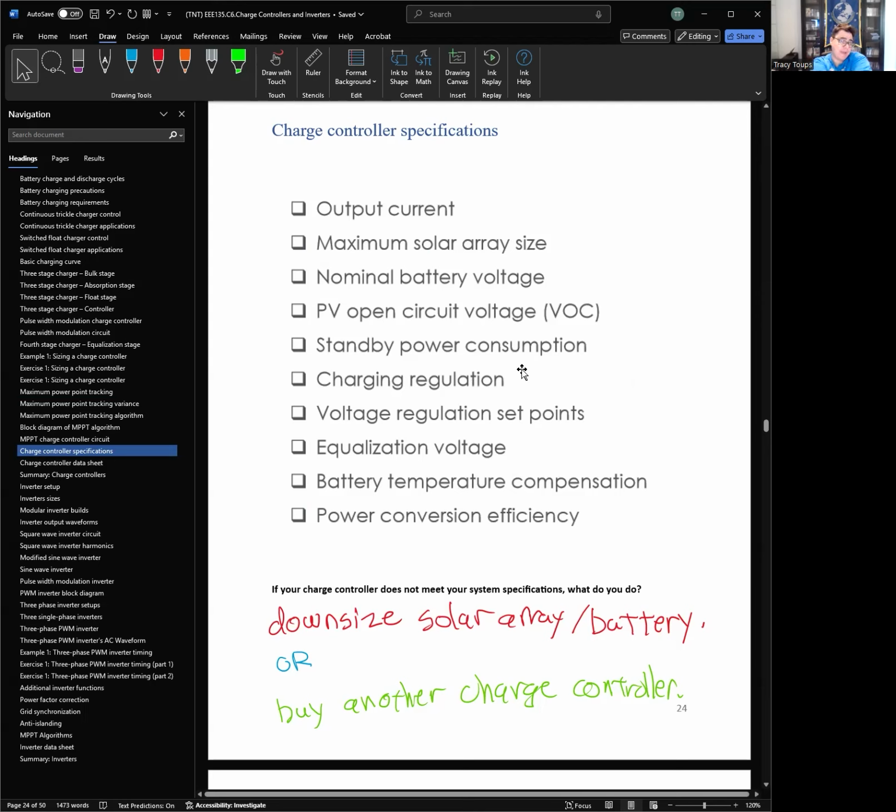So let's say nothing's happening, the battery's fully charged. What is the parasitic loss of just keeping everything online? It should be very low, like maybe 1% or less than 1% of the total power. But anytime you keep a controller on, there's always a very small amount of power you use just to keep circuits running. Just monitoring the system as a whole takes power.